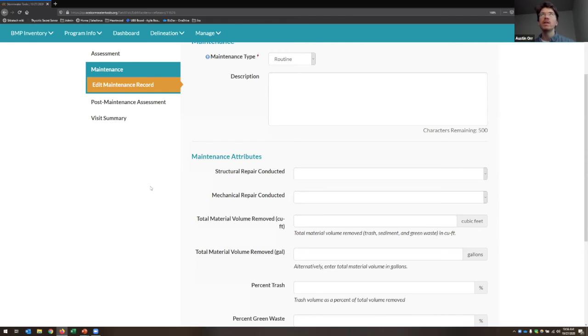And the reason we key on design drawdown time and BMP volume is those are two things that the client implementing registering a BMP in their system might know about that BMP. So they'll know how it was designed to function. They'll know the volume of it, the shape of it, and some design drawdown time. Or then maybe they know an underlying infiltration rate.